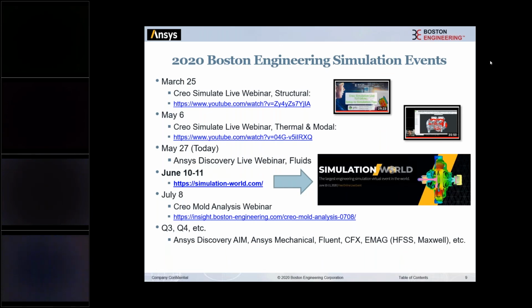Awesome. Well, Sam's got a question there. Is there a limit on wind flow speed? Yeah, so the focus here would be on incompressible flow. Depending on the application, you could be looking at a maximum Mach number of 0.3, maybe 0.5 or 0.7. But right now, it's really going to be looking at some of your low-speed airflow or water flow, incompressible.